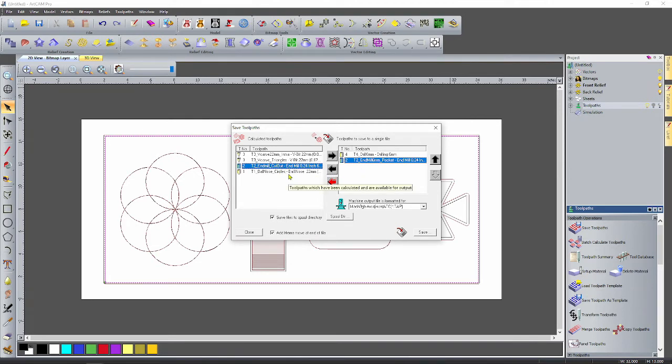And then the cut out is going to be the last one, so we have to make it after the pocket. Let's make the V carve one, the triangle, and then the end mill one, and the ball nose, the circles here, and then the cut out is the last one.